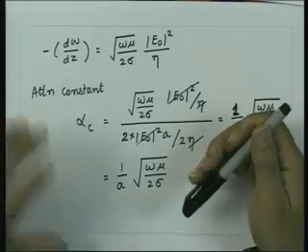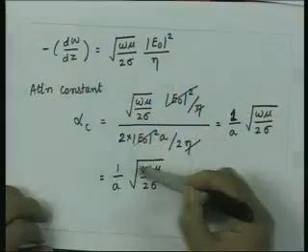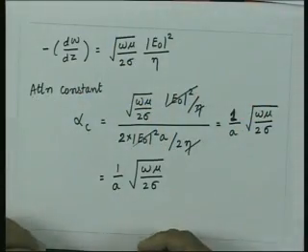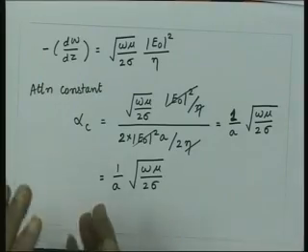That is the reason if you take any guiding structure like a coaxial cable or parallel plane line or anything, as you go to higher and higher frequency, the signals have more attenuation, because the attenuation constant is a function of frequency. So at low frequencies the attenuation constant is manageable, but when you use the same structure for carrying the signal at high frequencies, the loss becomes excessive and the signal cannot be transmitted efficiently from one point to another.